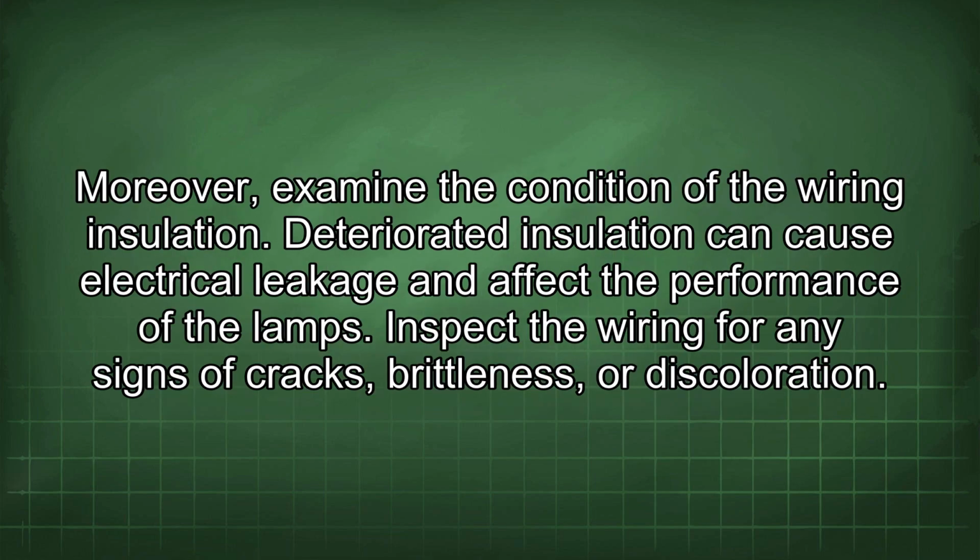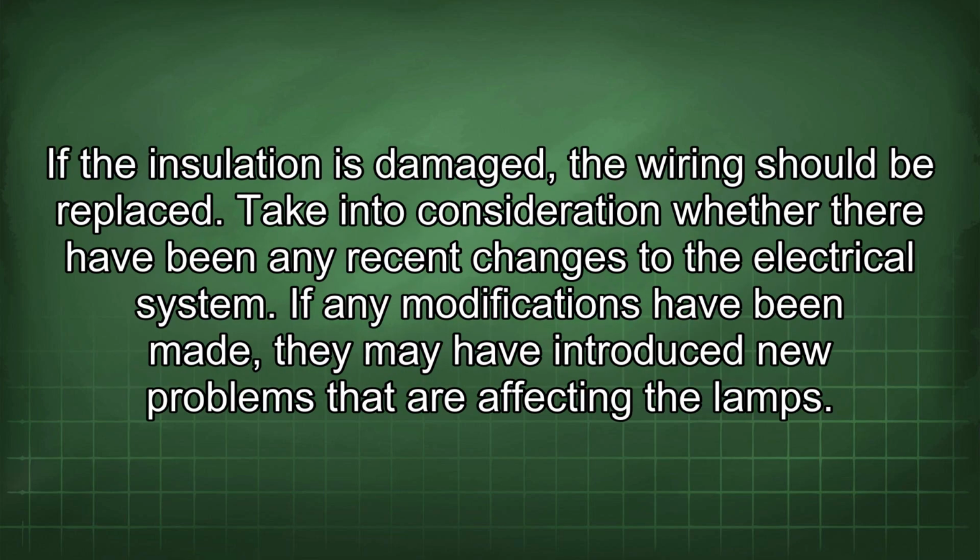Moreover, examine the condition of the wiring insulation. Deteriorated insulation can cause electrical leakage and affect the performance of the lamps. Inspect the wiring for any signs of cracks, brittleness, or discoloration. If the insulation is damaged, the wiring should be replaced.